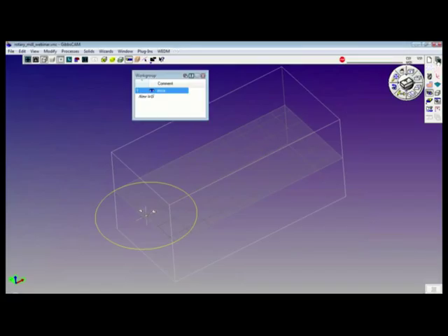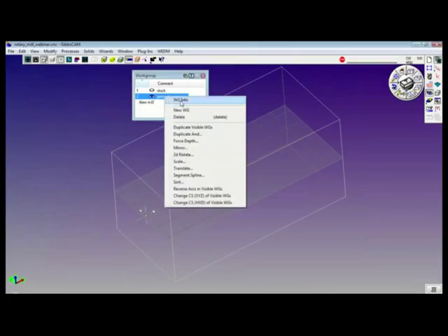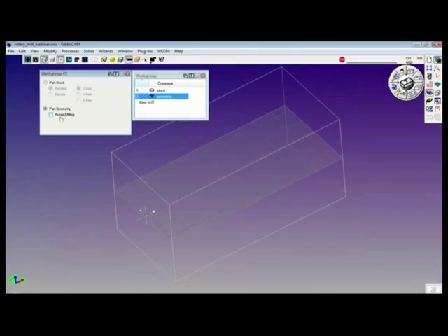So I'm going to build a new workgroup, and I'm going to name it geometry. I'll right mouse click the geometry workgroup, click on workgroup info, and since I'm going to define geometry that is going to be wrapped around a cylindrical shape, I'm going to turn on rotary milling, and by turning on rotary milling, it activates the wrap geometry tile right up here in the taskbar.